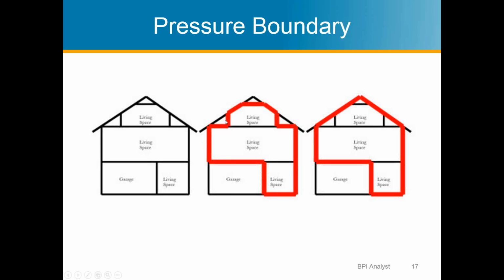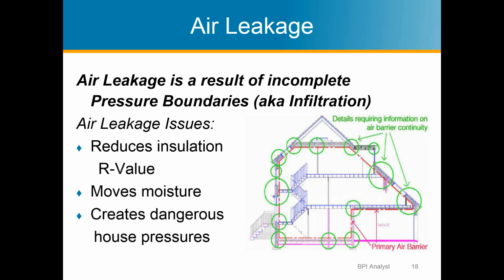Typically it's done more like this, but a lot of times when it's done like this, this vertical piece does not have the 6 sides. So it's just an issue in modern construction. A lot of times the building scientist community wants insulation in the roof deck, and with the roof insulation in the roof deck, hopefully there's an air barrier there too, and our ductwork in the attic is now in conditioned space, so it loses less energy. But anyway, that's pressure boundaries and air and thermal boundaries.